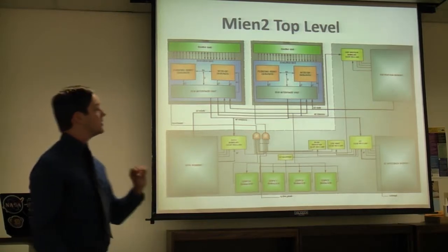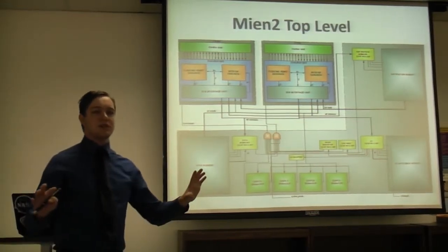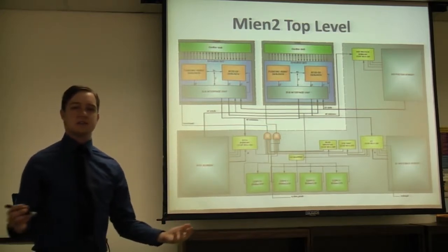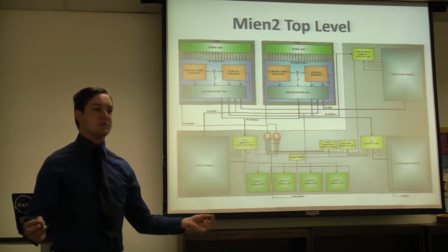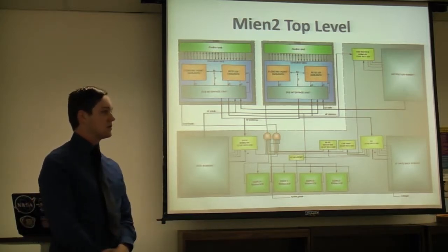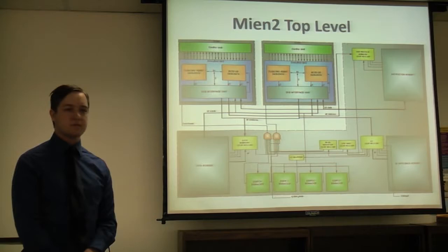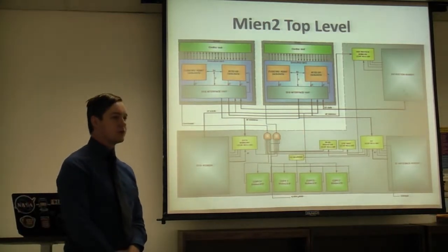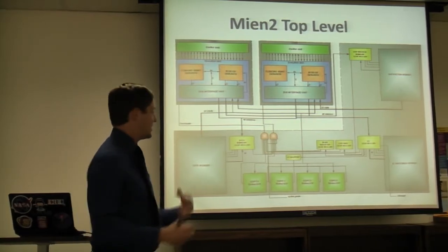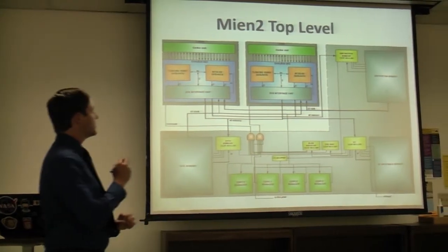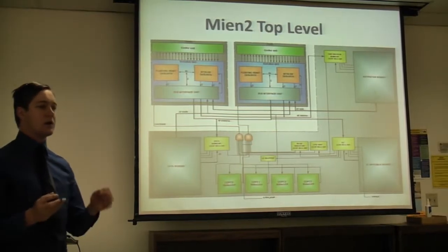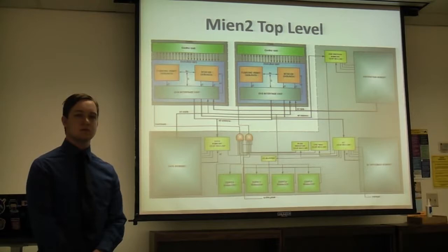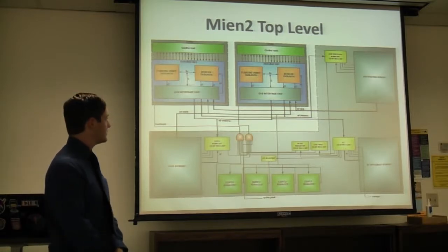The programmer... without any modification to the original code, this will run on a single core, as it would run the baseline. So our baseline just runs on core 0, where we make a new program in order to run both cores. It explicitly calls the other core. Both cores have their instructions in instruction memory. Core 0 tells core 1 where in the memory to begin executing when it's enabled. Thank you. That really elaborates.